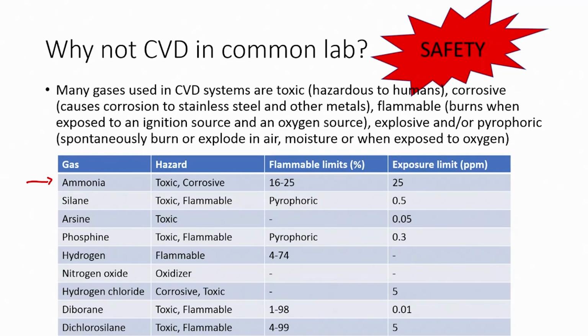So, in short, what we understand is CVD can be used for depositing an insulator or an oxide layer; the insulator is an oxide or silicon nitride layer. It can also be used to deposit silicon, and it has advantages over PVD in terms of film quality and better step coverage.